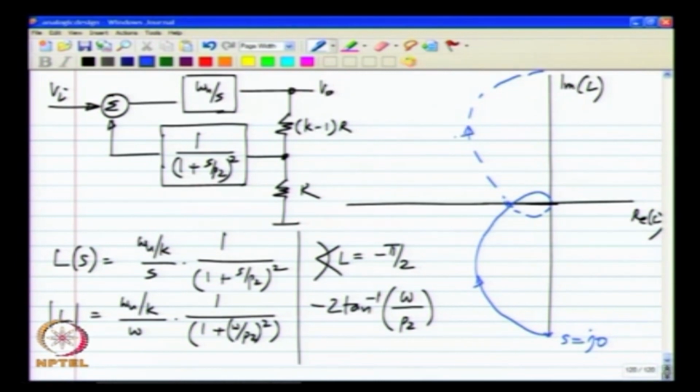Okay. So, that is what happens, and this point and this point are the same. So, I will just show some connection there. Now, does this enclose minus 1, 0 or not? Now, we can't tell, because the way the shape is, it could enclose or it could not, depending on the parameter. If minus 1, 0 happens to be there, it is not enclosing it, and if the minus 1, 0 happens to be in that region, it is enclosing it. Okay.